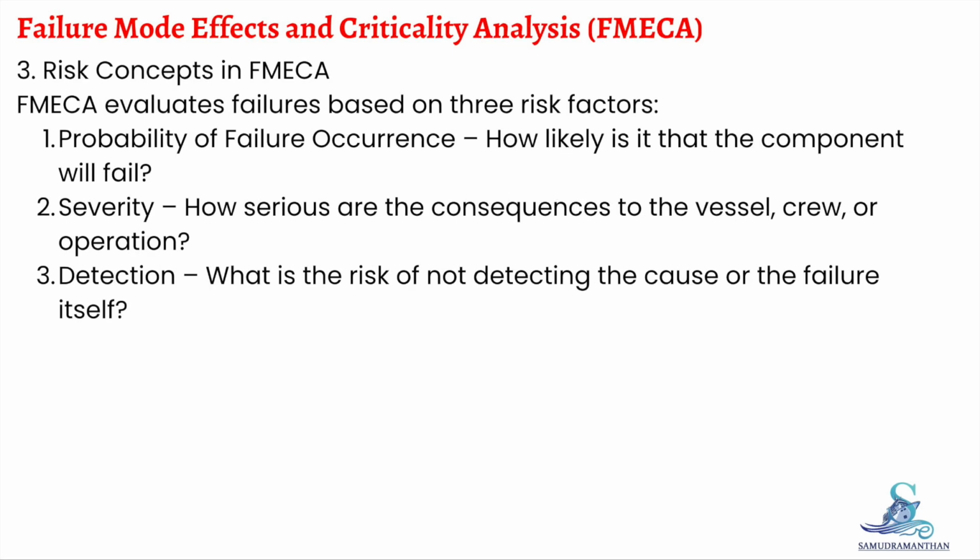FMECA also evaluates the risk associated with each failure mode. The three main risk factors considered are: first, probability of failure occurrence. How likely is it that the failure will happen? Severity. How serious are the consequences for the vessel, crew, or operation? And the third one is detection. What is the chance that the failure or its cause will go undetected before it becomes critical?